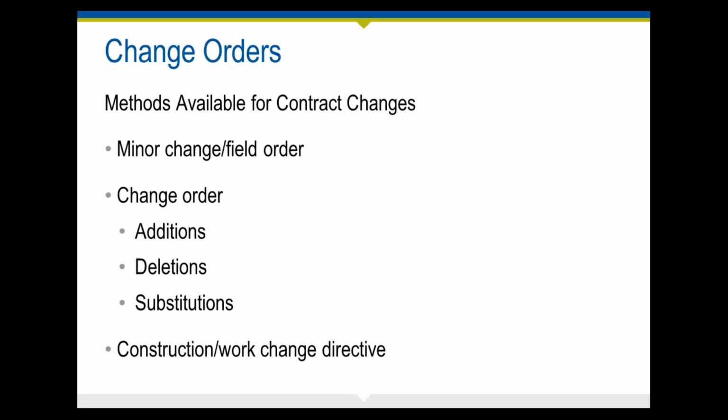affect that, if you agree that it indeed meets the design concept and makes sense and so on, is number one, you need to make sure that you're being paid for that additional service. And number two is to make sure that there is a formal change order that is indeed executed by all parties to reflect what that changes. You don't want to be in a position of having agreed to a substitution by way of shop drawings only, because shop drawings, as we said earlier, are communication tools. They're not contract documents. So you need to be aware of what the implications are if that is indeed the route in which the contractor is proceeding. It is perfectly acceptable if there's going to be a substitution and you think it makes sense based on the review and so on, but make sure that it is reflected in a formal change order to make sure that the contract documents reflect what is going on.